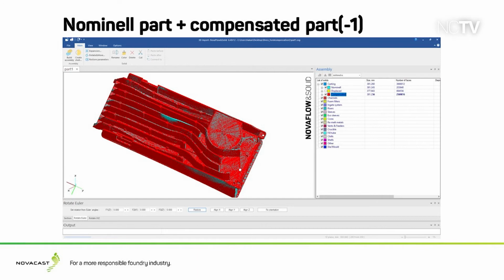In this case, the part was designed with the distortion behavior, and then we have to compensate for that distortion behavior. That would be possible to do. Of course, if the distortion is too much, it could be a problem to design the tool, because there will be a kind of undercut or something like that. So that would be a problem in that case. But that is something you have to look at, of course.